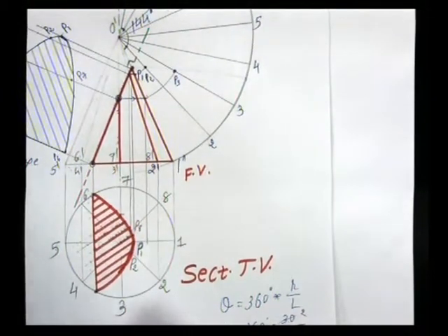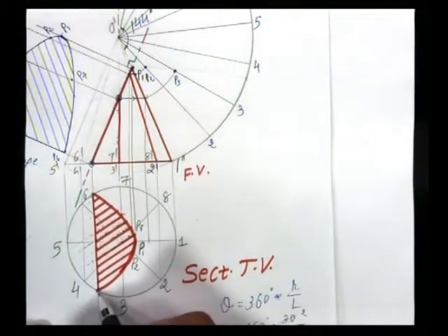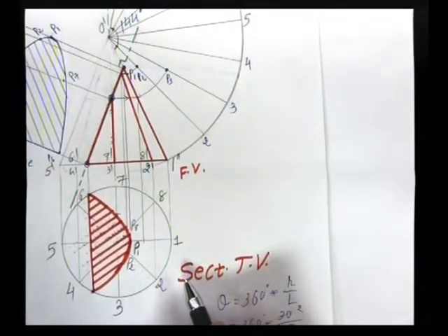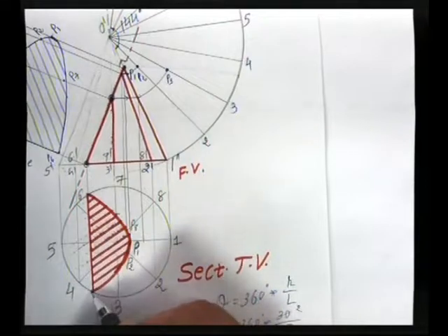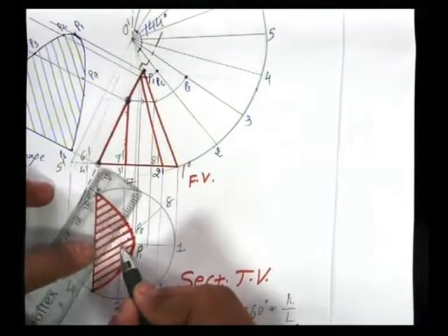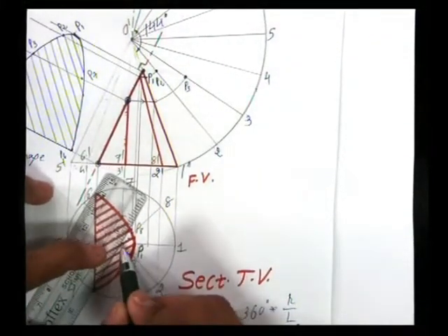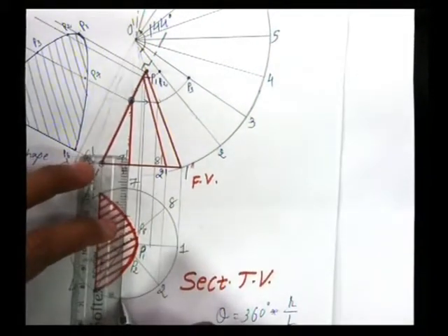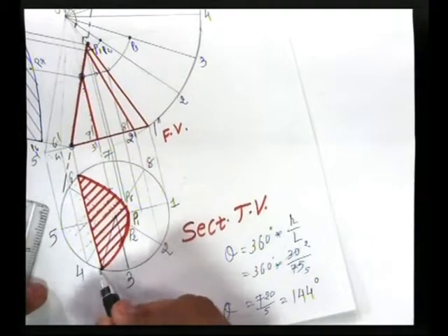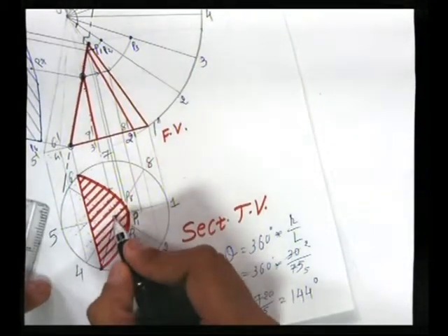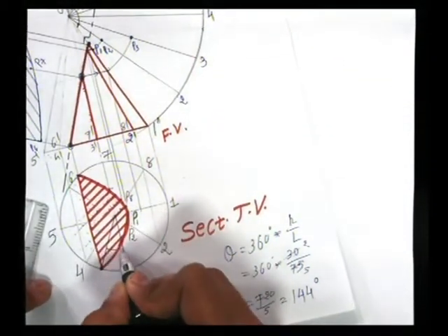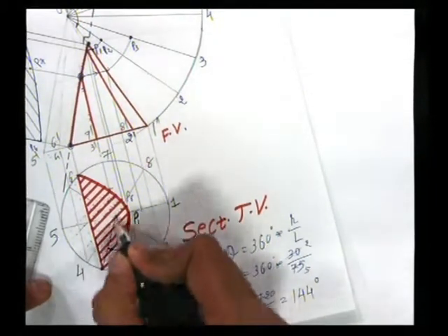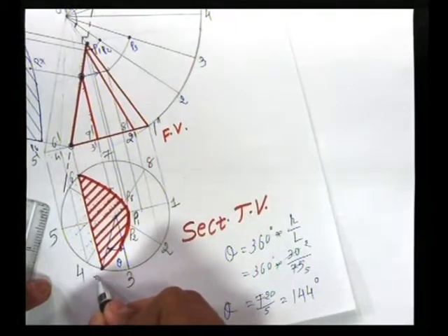So for that we need to transfer the distance of this point over this periphery by having its basic concept, that is length of arc. Arc length is equal to radius into theta. So for that, measure this angle, extend this line like this. This point we join with the midpoint, measure this angle. This angle is theta, right? We know this radius, so say this is point number M.